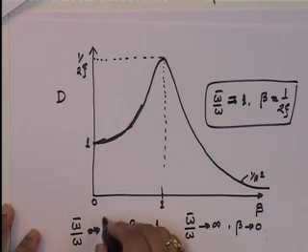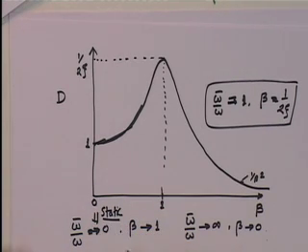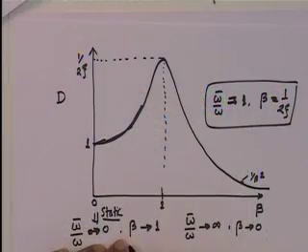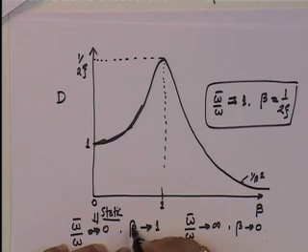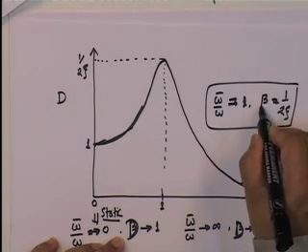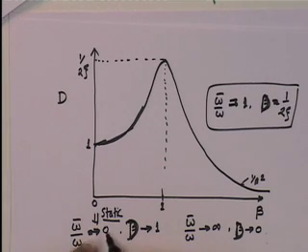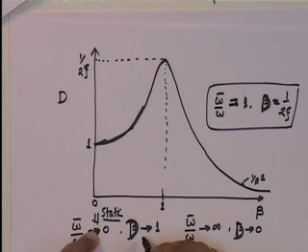What is omega bar upon omega tending to 0? This implies static loading, because omega bar is 0. In other words, the excitation is not cyclic at all, it is a constant P naught. And therefore, sorry, this is not beta, this is D. D tends to 1. I am so sorry, I have made a mistake here. D tends to 1. If you have a static load, the dynamic amplification tends to 1.